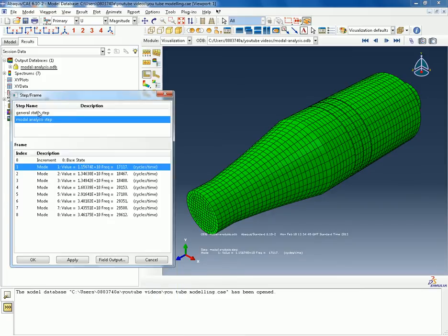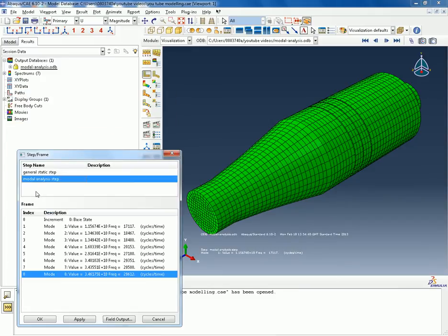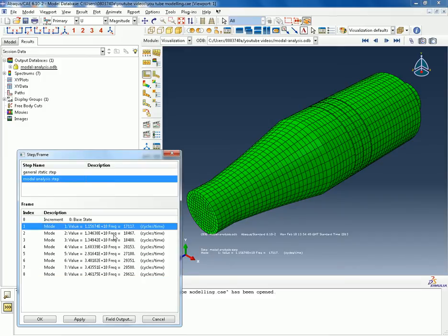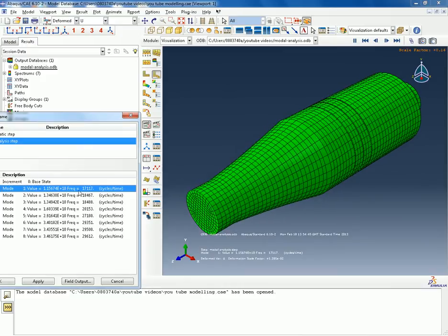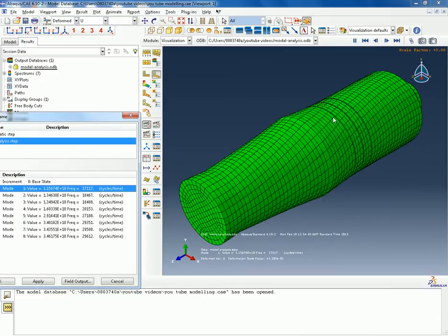And on the model analysis tab, we can see a number of modes of vibration being extracted, and the value in here represented the resonance frequencies in hertz. To view the mode shape of these resonance frequencies, all you have to do is to activate the animation. So as you can see, for this mode of vibration we got the first torsional mode, because we only have one nodal position along the structure. Nodal position, the place where the response is approaching zero value.